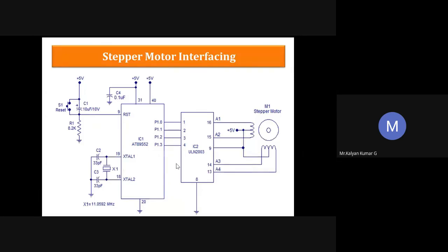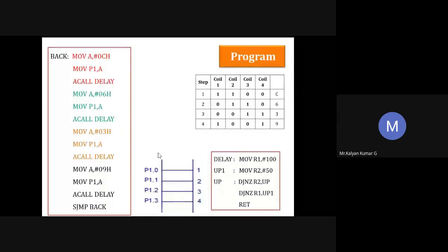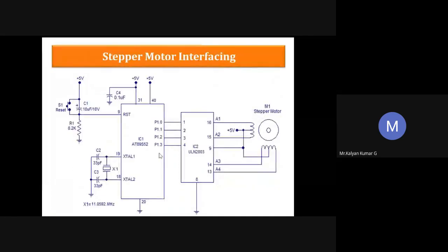And here we have the stepper motor. It has 4 keys given, and the 4 keys are interfaced to port 0, port 1. In order to control the motor operation, you can use any port 1, 2, 3, it's up to you. The keys are normally used to start and stop the motor, and apart from that, also to select whether you make the rotor run in forward or reverse direction.